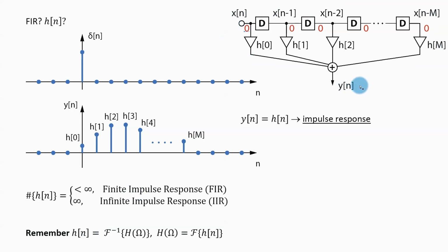the time domain. Actually, this process of designing a filter in the time domain is a little bit involved. I will be talking about it in the next lecture, but the main idea is this. Now, the last thing to mention is that this structure can work in real time. As those numbers are coming in, something immediately appears at the output. To tell you the truth, this typically introduces some time delay, and typically this is set to be half of the number of these delay elements.